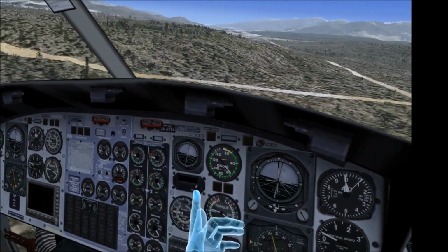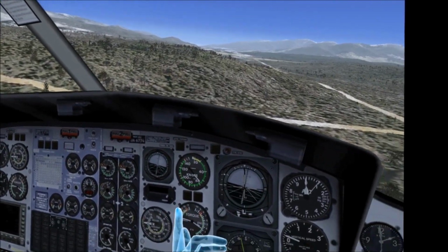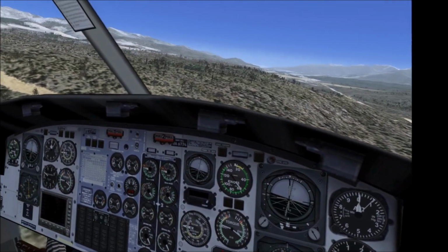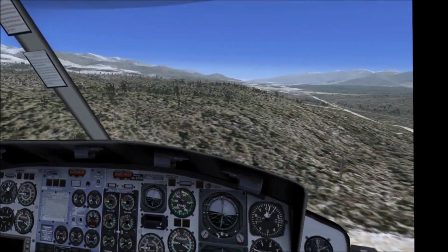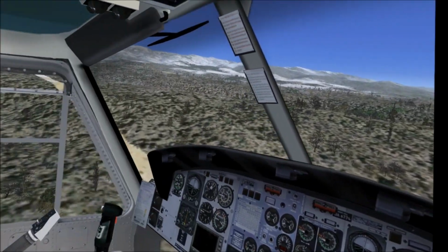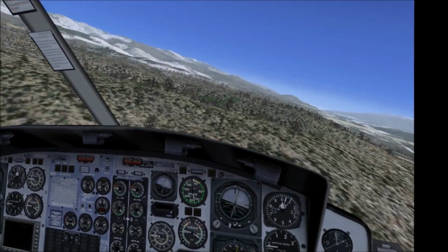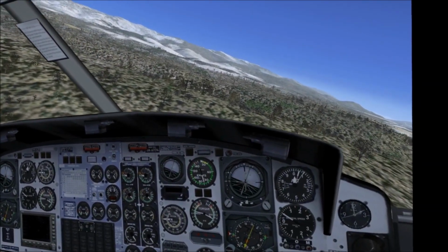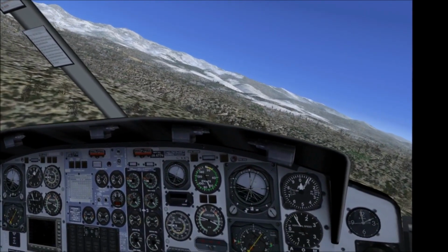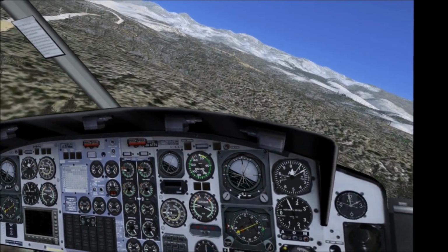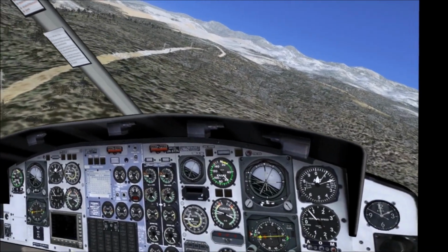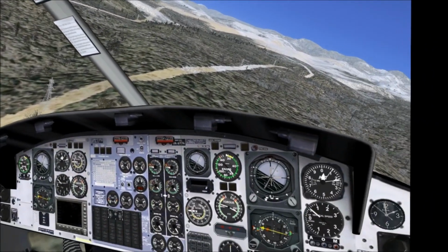But either way, we did have a rate of descent at max power, so that means we don't have OGE power. So I think this weight combination is going to be good for what we're looking for. We just have to try to adapt for that artificial power limit. Now, I'm not sure if I broke something, but the rotor RPM and engine RPM did rapidly decay as if we had a dual engine failure.